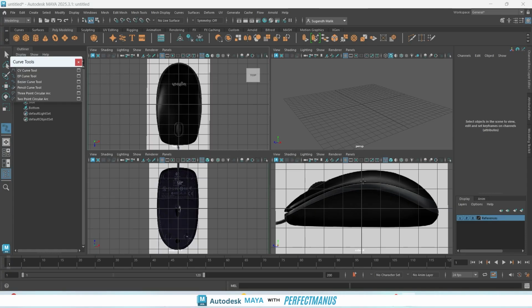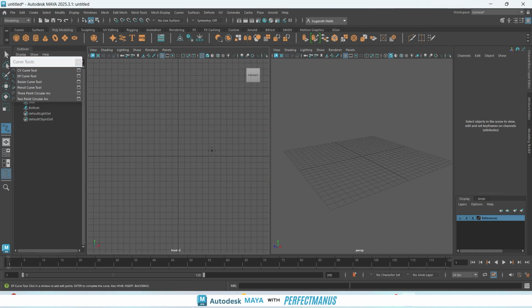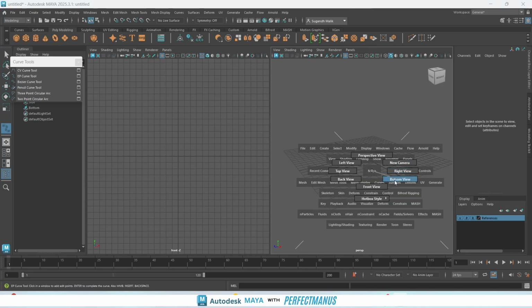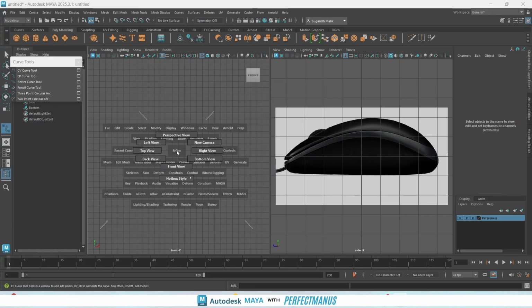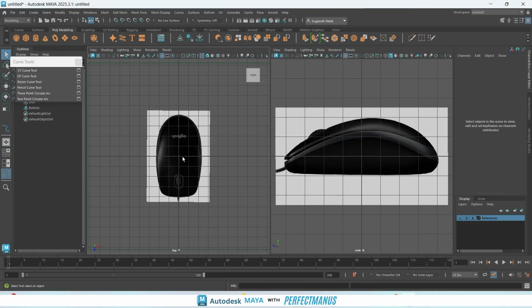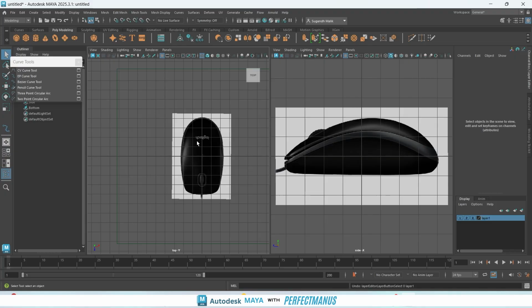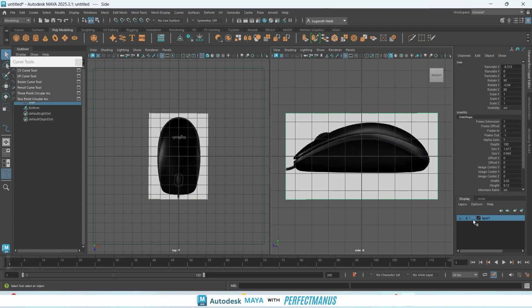You have to follow it in one axis, but you can also watch in another axis. So for this one, I'll be focusing more on your top and your side view because this is the one I'll be creating first, okay. So by simply clicking here, it will be into your two view mode. So for here, I need your side view, right view, okay. And for here, by holding your space and your right click, you will see these options and it will be top view, okay. So here, you need to make sure that they are clickable again because you need to focus them in. Now again, make them unclickable.